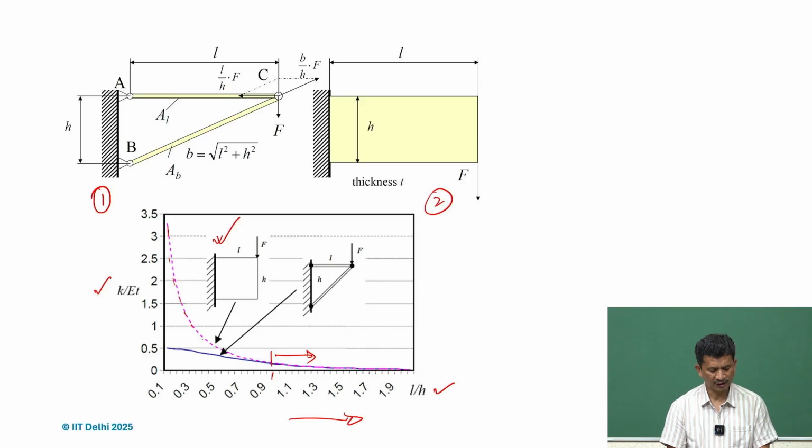And what we realized is that maybe the truss construction might be preferred because of the ease of manufacturing and how it can be constructed. Because the stiffness-wise is the same, and a very thin sheet will have other kinds of problems. It is prone to warping if the forces are really high. So, for that reason also we tend to use truss structures.